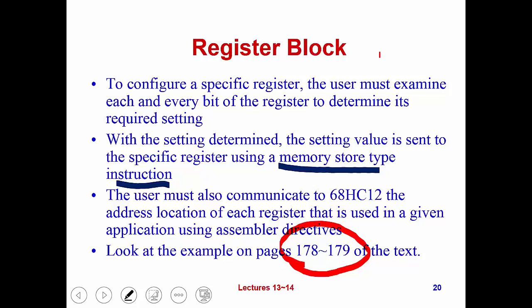Then we load this value to accumulator A. You see the third instruction here. We put a pound sign because we use EQU, and EQU never involves memory. When you hope to load the numerical value, which is 80, into somewhere, you have to put a pound sign in front of the label. So we put a pound sign in front of A to D initialization. That's going to load 80, this numerical value, into A.